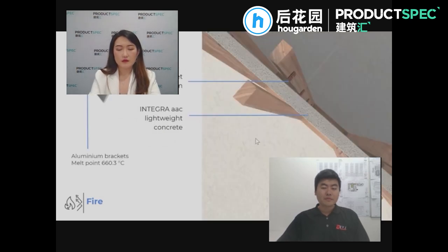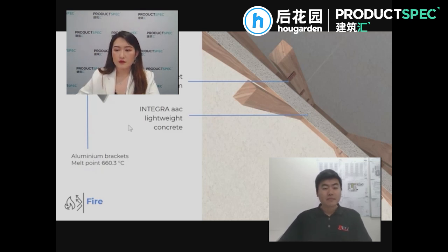So once again, we look at the walling system. It's constructed exactly the same as we did in the acoustic lab. But the thing with these, I must make a note about these brackets. Now, when we build this wall here, our proprietary brackets or specific brackets for our system are made of aluminium. And that's really important. If you make these out of galvanized metal or metals with a higher melt temperature, they don't melt. And we want them to melt.